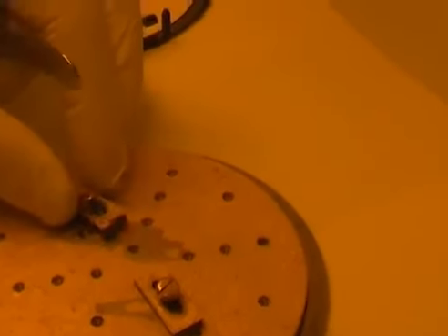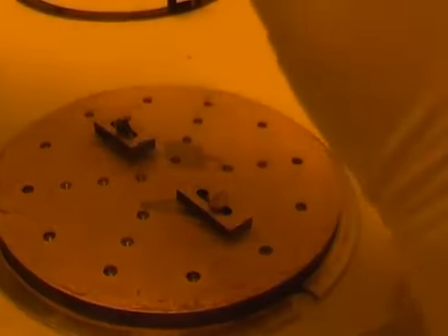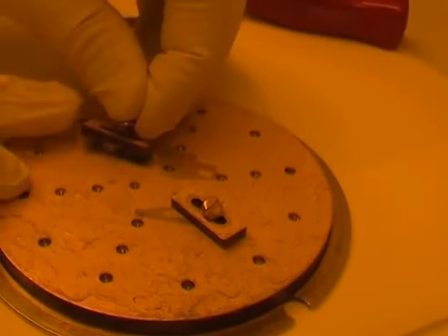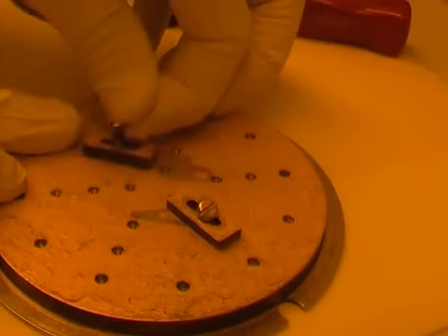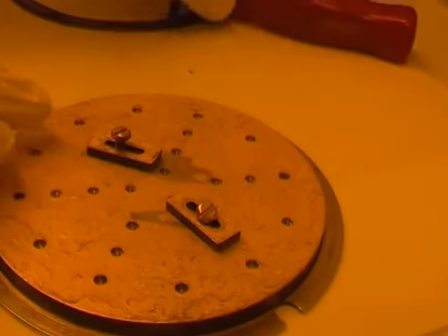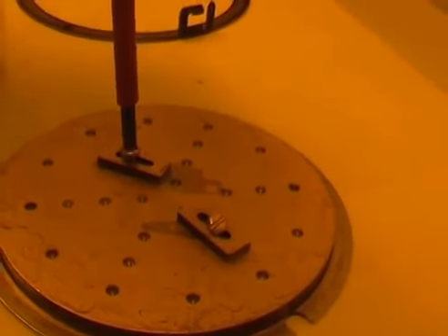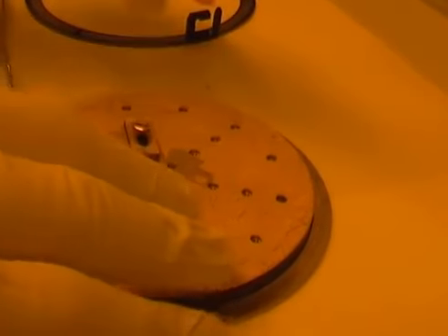And so after deciding where to put more or less my sample on the holder, then I start to put the screws and the clamp down in the 2 holes that I decided to use. At the beginning I don't put them down all the way, but just loosely. Ideally, it's always good to use at least 2 screws for each sample in order to make sure that the sample is kept horizontal